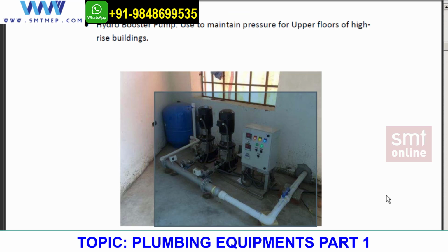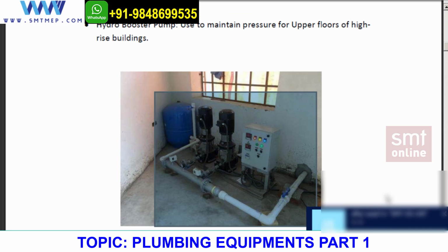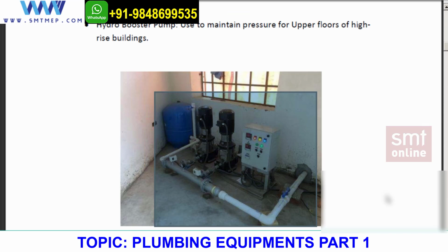Because the floor FFL height is what? I'm talking about residential; we consider 10 feet. Commercial might be 12 or 14 at maximum, isn't it? It depends. If it is an airport or something, it might increase even more. So do you think I get the required pressure because of this much gravity force? On the 6th floor it will be very low pressure at the fixtures. Again, the water travels to the 5th, where it will be somewhat higher compared with the 6th.